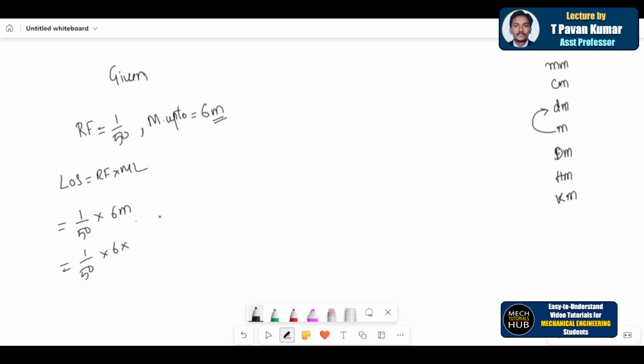Now to draw the sketch on a sheet of paper, whatever might be the question, we need to convert everything into centimeters. Whether the question is given in meters or kilometers or decimeters, you have to convert everything into centimeters, because your scale can measure only centimeters and millimeters. Either you can convert to millimeters also, not a problem, but always try to convert into centimeters. It becomes easy for you to construct the scale.